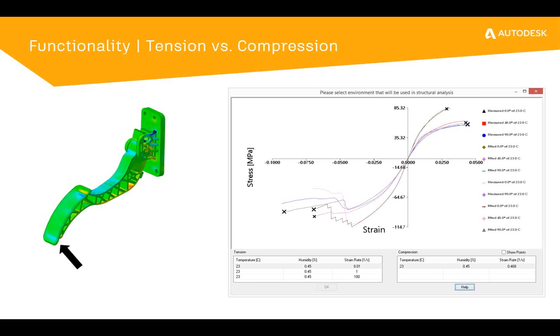And so we have a fan gate, and we fill so that all the fibers are pointing in one particular direction. Now we want to cut out two coupons from that plaque. One coupon represents the flow direction, and one coupon is 90 degrees, or orthogonal, to that flow direction. It's those two directions that are the basis, the minimum input required in order to perform a nonlinear analysis using Helius PFA.